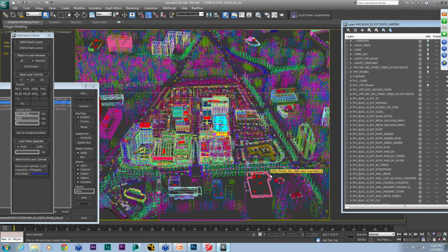Yeah, I think for glass surfaces like that, or for walls, for example, or for complex geometries, the shell is the fastest and easiest way. It definitely is the way you solve that problem. There are scripts that will allow you to select objects and normalize the normals overall, or see really quickly which ones are flipped, and then on button clicks go through and flip those normals. So there's that technique, but that technique takes a lot more time. And I would definitely say your strategy of shelling is probably the best technique.